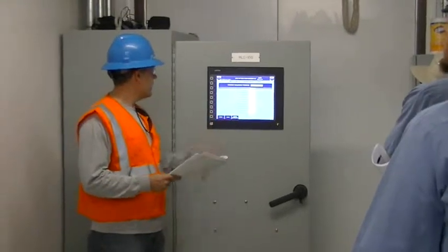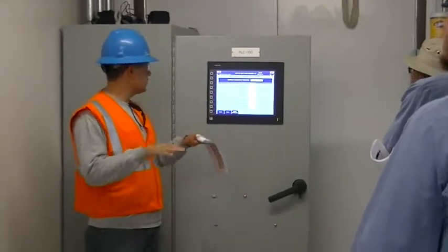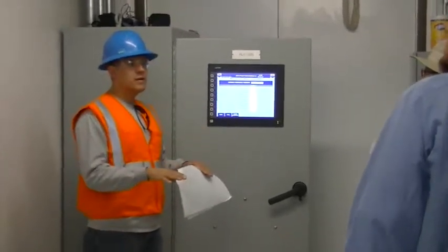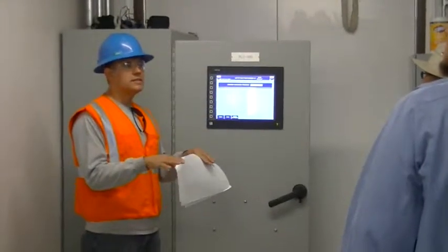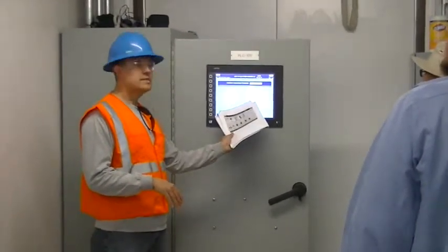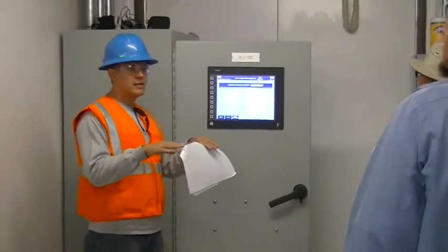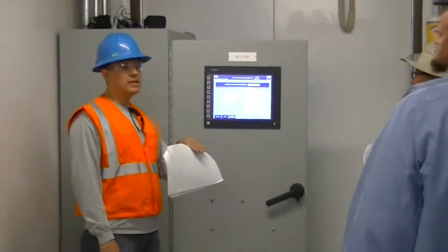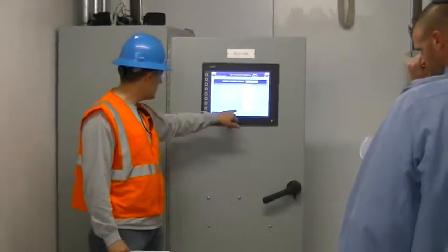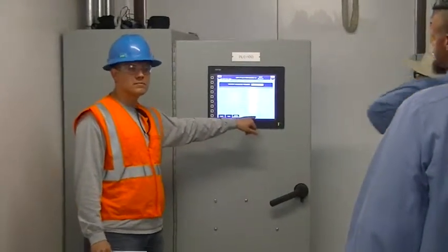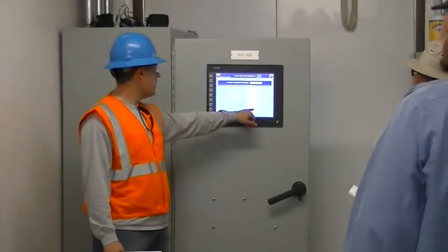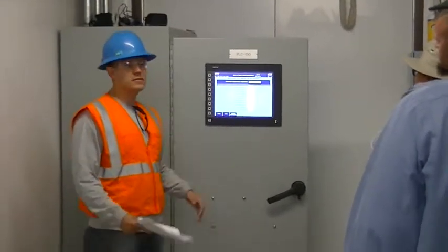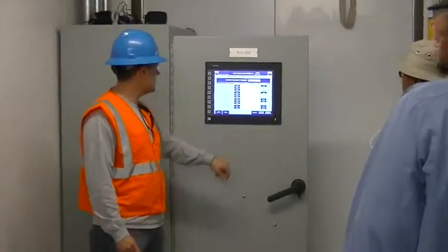Now it'll shut off after it drops to its minimum speed. So it's maintaining pressure. Both drives come down to 42 hertz, and they're sitting there. After they sit there for the 60 seconds, the 1 minute, the second VFD will drop out, and the main VFD will be running. Now that one will not shut down until you hit this high pressure set point of 70. And then you have your VFD max speed, which is 60 hertz, and then your minimum speed setup, which is 42 hertz. And that's adjustable. So you can adjust that in adjust set points.